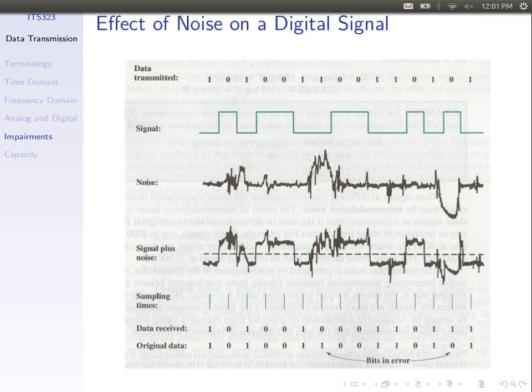That is, if there's noise which has a magnitude of 1 or more, in this example, we'll get a bit error. It takes our +1 to negative, a magnitude of 1. Similarly in the other direction, if we transmit -1 and it goes positive, that'll be an error.